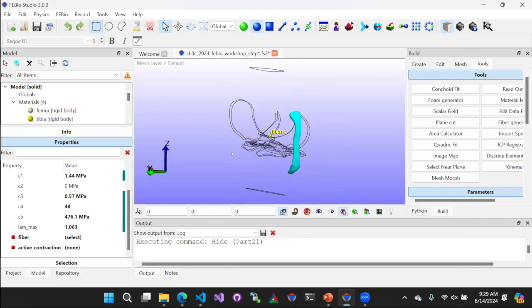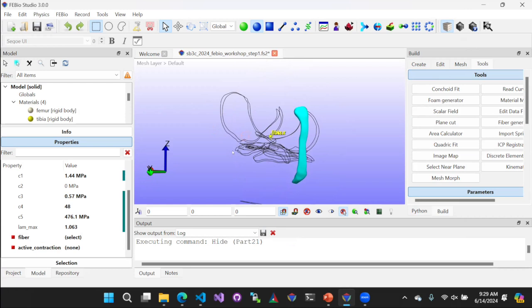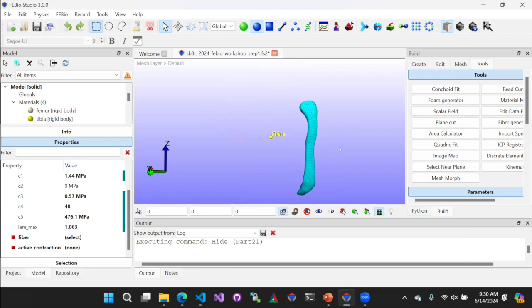Once you have that, remember we have our Z shortcut key to get rid of all these black lines. And then we do want our mesh visible, so let's select the M shortcut key to bring that back. Then make sure to turn that off, otherwise we're going to run into some strange issues. Again, make sure this option is off once you've hidden all these parts.